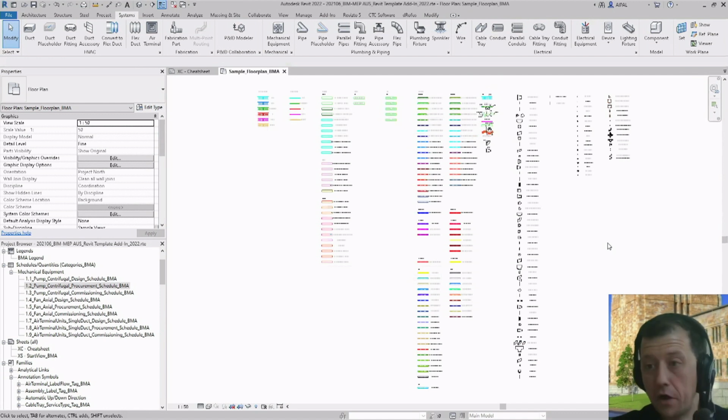Because we maybe have an asset replacement and we need to replace a pump from manufacturer X with a pump from manufacturer Y. And I don't want to have completely different parameters on it, because this is just the Revit schedule, so that is pretty easy to handle. But when you think of a facility management system in the background somewhere that is connecting to these parameters, you can break a lot there.